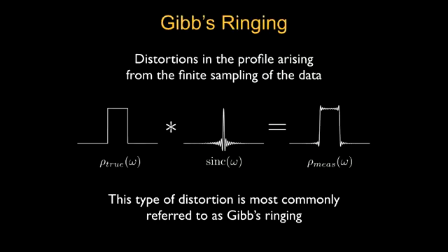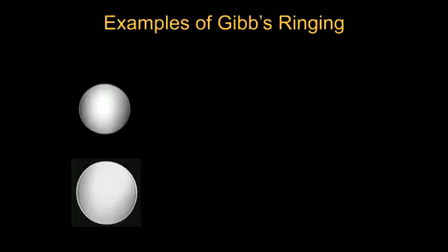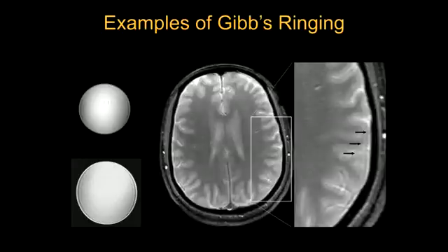So if this ringing is too much, then there is a lot of oscillation in the object. And sometimes you can actually clearly see it like this. I don't know if you can see it clearly, but there's a ripple here. That's the so-called Gibbs ring. Even in diagnostic imaging, sometimes you can see those ripples. Those are not real images. It's called a Gibbs ring.